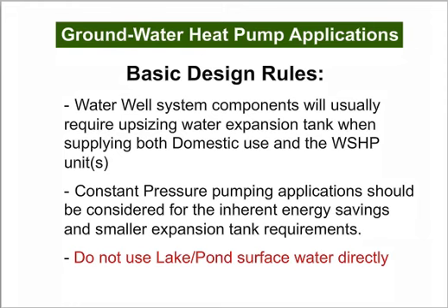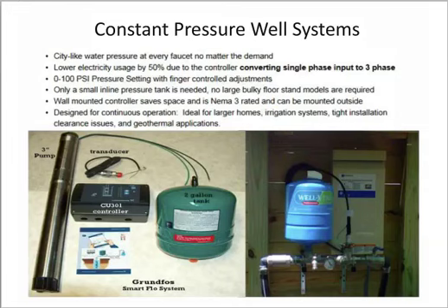Word of warning. Never, ever, ever use lake or pond or any other kind of surface water directly through any kind of a geothermal heat pump. The hazard and risk to that is, well, you don't know how the water quality will be. It might be okay today, but what will it be tomorrow? And you can actually install something that can then turn out to be a nightmare for the end user. So again, never, ever, ever use surface water or lake water directly. And in most places, they don't allow you to pump lake water through anything, a heat pump, and oftentimes it's now even difficult for irrigation.